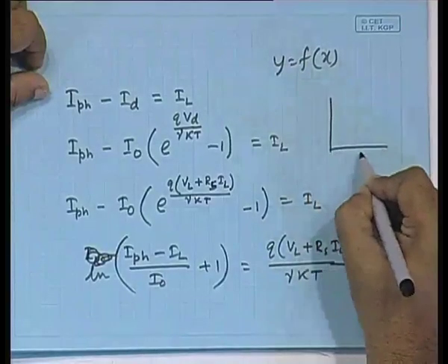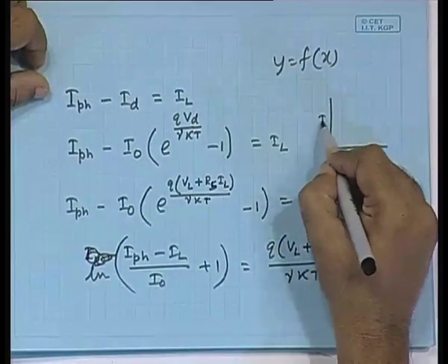But if you are used to that kind of values, take them, no problem, because you have done problems using PN junctions. In case of the photovoltaic panel, it will be slightly more than that anyway. So, you can solve and obtain the characteristic graph, plotting it with V on the x axis and I on the y axis.